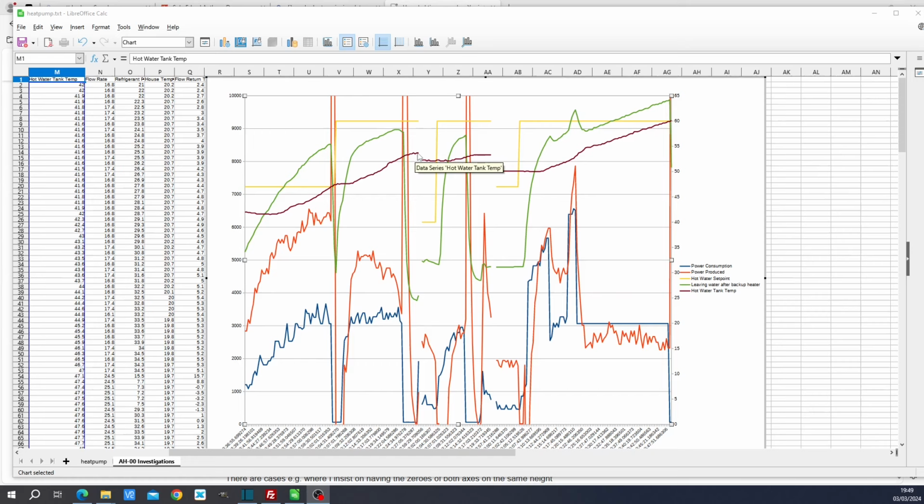It doesn't kill it as fast as it does at 60 degrees Celsius, but we do maintain a temperature above 50 degrees Celsius for a long time. So from 12:20 p.m. until 2 o'clock in the afternoon, indeed until midnight the following night, we had temperatures above 50 degrees. I think that's sufficient to do this. And yet we're not able to adjust the disinfection temperature. So it seems like the backup heater is essential to do the disinfection routine.